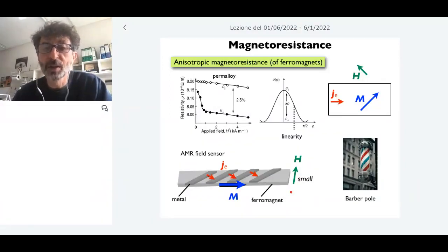So it's a very, very soft magnetic material. As I told you, permalloy is one of the alloys used to make thin films because it has vanishing, zero magnetostriction. So a long bar like this, very thin because it's a deposited film. Then, if it is very long, the magnetization will tend to stay aligned in this direction here.